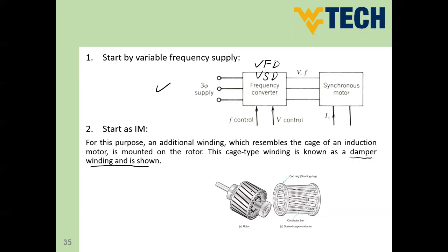Okay, so what is the concept? How is this motor starting? I'm not going to discuss in more depth how the induction motor starts, but you need to know that the induction motor is a self-start motor. So once you supply the three-phase induction motor, it will start with a speed called rotor speed, and this rotor speed is very close to synchronous speed at no load. Very close by a small value called slip.